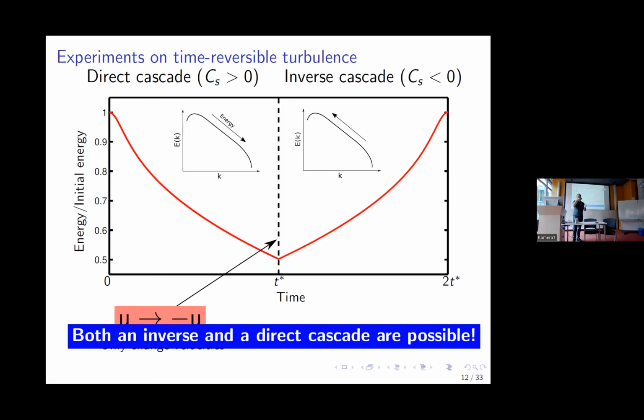And remember that there is a stepwise process in the energy cascade in which things forget where they come from or where they're going. So the model is not relevant for this. It's just a way to make the system reversible. You can actually do this experiment at high Reynolds number, and it will work the same. Even though you have dissipation in the small scale, you change the sign, and you will see part of the flow in the inertial range going up.